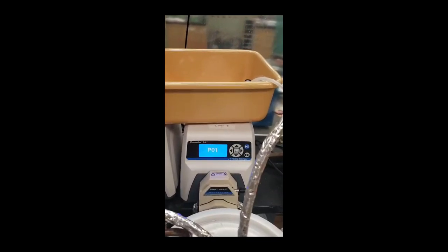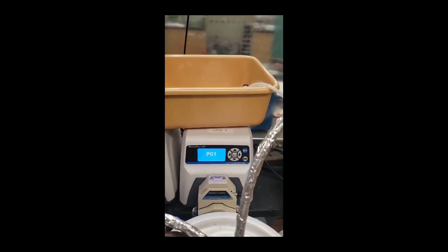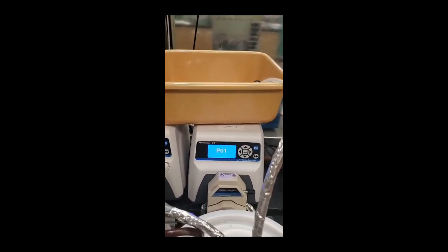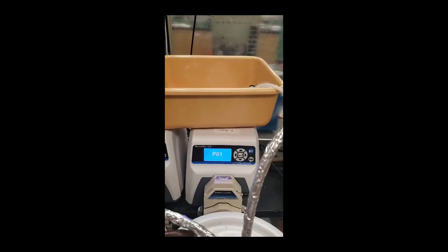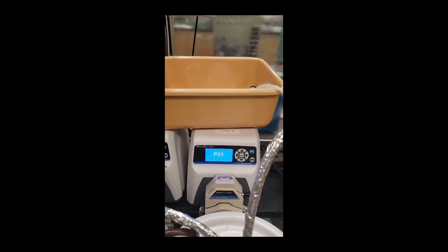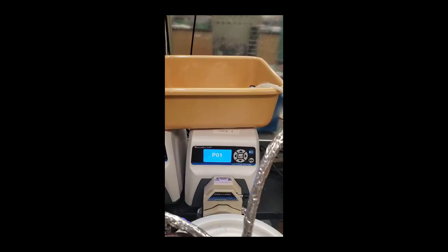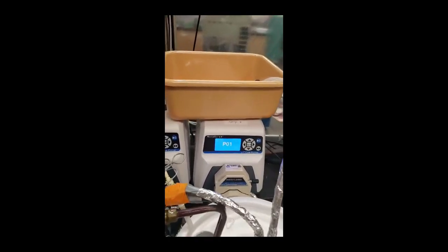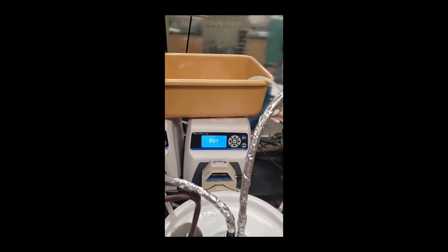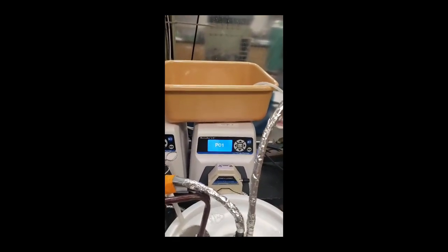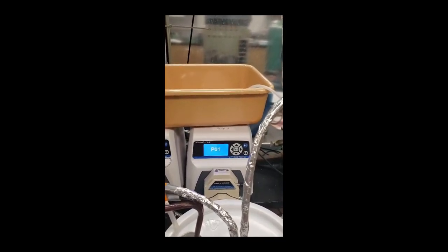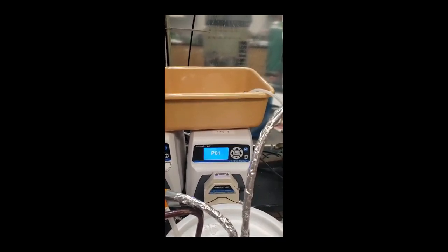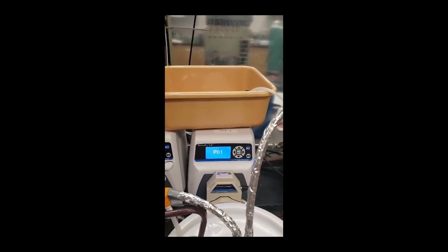How the pump reads the command or the order is something that the instrument will give you in its manual. For example, the manual of this instrument says that if you type H, that means halt the pump. So you basically have to look at the manual of your instrument or call the company that you purchased the instrument from, and then you will know how to define the command based on the language that the serial communication works with.